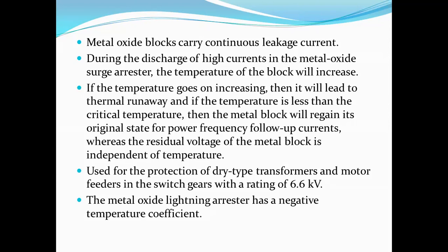Okay, then it is used for the protection of dry type transformers and motor feeders in the switchgears with a rating of 6.6 kV. So these ZnO, or zinc oxide arresters, are used for the protection of dry type transformers and motor feeders in the substation with a rating of 6.6 kV.